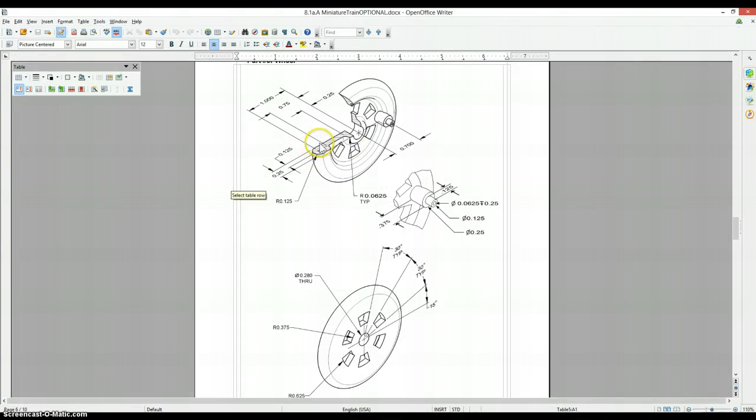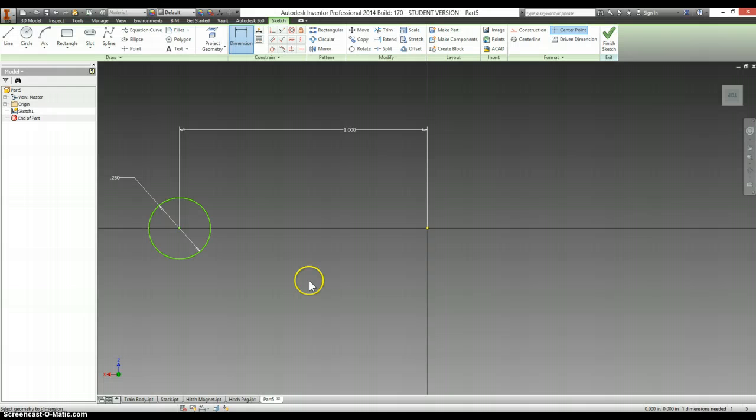And if I draw a line across here, it actually doesn't tell me in this view where this line is, but if I look here, I know that this hole, which is what I'm kind of drawing, has a diameter of 0.28. So if I keep that into consideration, from here to here, half of 0.28 is 0.14.